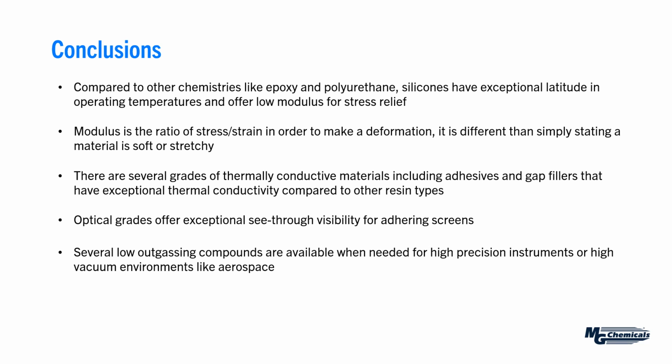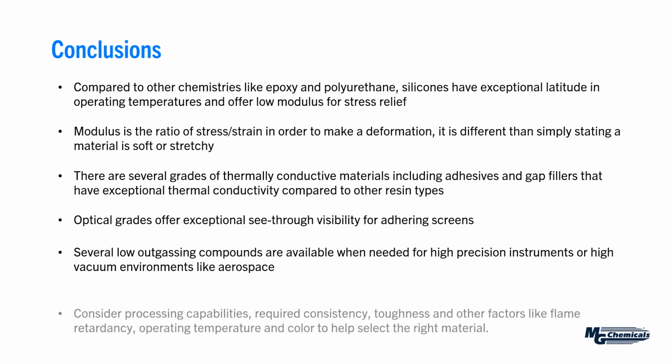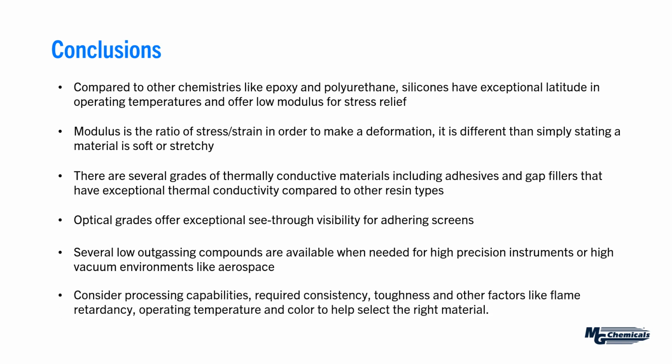Several low outgassing compounds are available when needed. And that's for things like high precision instruments, or if you're in a high vacuum environment. So aerospace is very popular, where they may be in an exceptionally low pressure environment and they don't want outgassing during operation. And then finally, we need to consider the processing capabilities, the required consistency, the toughness, along with other factors like flame retardancy, the operating temperature, and color, in order to arrive at the right material.